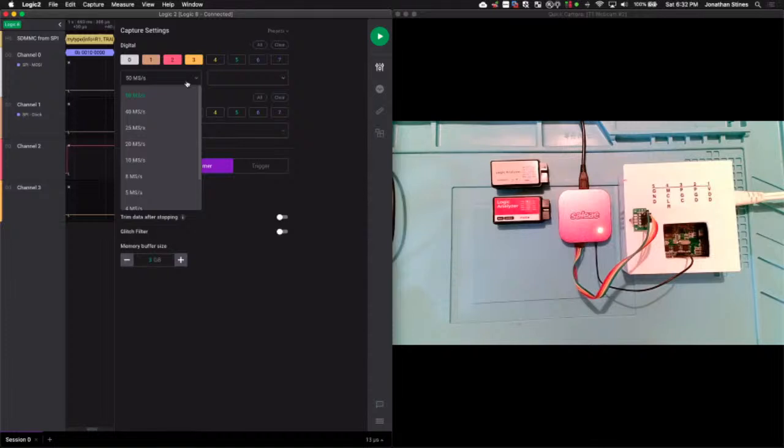What I will do is, if the sample rate's not high enough, I've actually had my Saleae start throwing errors and tell me that it was missing data, that it wasn't sampling quickly enough. I had that just recently looking at some data flow. As soon as I kicked it off, it threw an error telling me it was a missed sample rate, so I was able to crank it up until the error went away. Sometimes I also just crank it up if I know for a fact that it's a high-speed device that's going to be generating a lot of fast traffic.